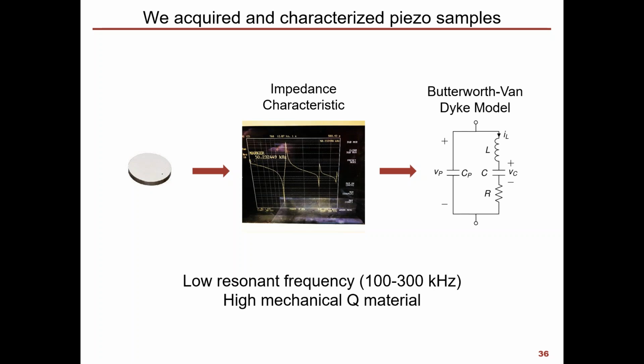It's possible that over time that starts to relax. And if it does relax, then we start to lose some of our piezoelectric properties. I have not observed or studied this myself. This is just forecasting what I would expect to happen. That's a very important question going forward. Besides losing the polarization, does it also become more susceptible to cracking over time? Because it's a ceramic material, once it cracks, it's done. There's no going back once it cracks. It'll be interesting to see what can be studied about that going forward, for sure.